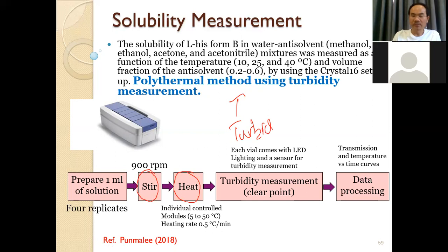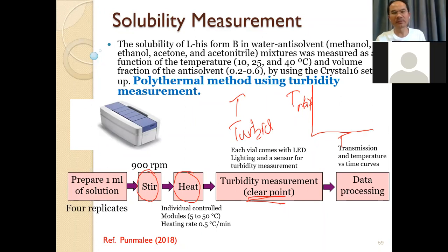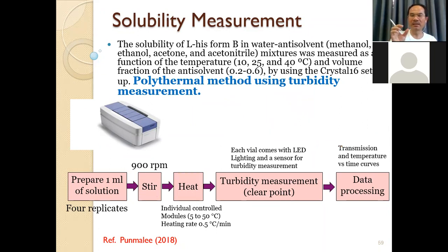For this case, we check the temperature and turbidity, like we initially have with the solid and liquid. The turbidity point is the clear point. When all of the solid dissolves into the solution, you record the temperature at that point. At that point the temperature is the saturation temperature. And with this technique, you can obtain the temperature that correlates with the concentration.